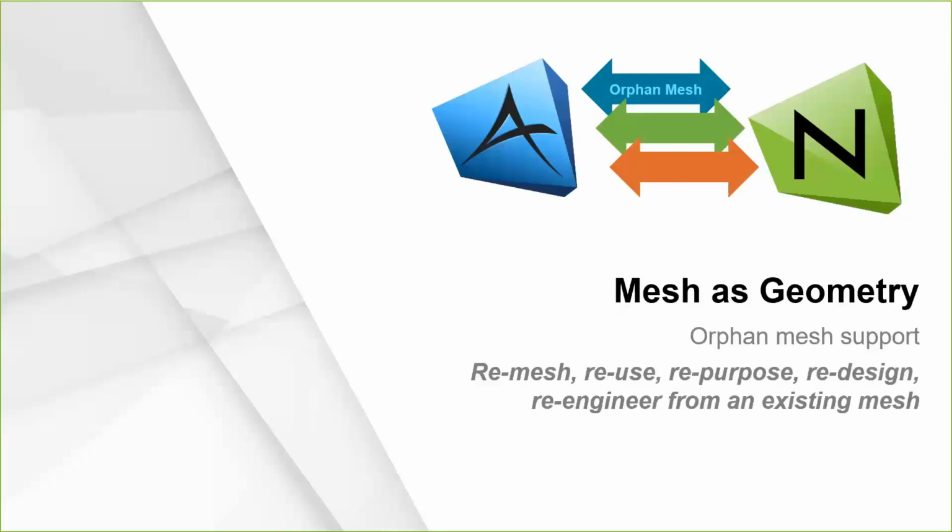And sometimes it's because you want to leverage the investment. It costs money to make a finite element model, right? So you want to leverage the investment, the time and the money that you put into this existing mesh, partly because that mesh represents the behavior of your structure. Your structure is physical. Your finite element model is an abstraction of that, right? But you've created an abstraction that accurately reflects the behavior. You've used it for margins of safety. You've correlated it to tests. You've written certification documents based on it. So you feel that if I start the next phase from this existing mesh, I'm having more of an apples-to-apples comparison, right? Because I'm actually starting from the behavioral representation rather than the physical representation.